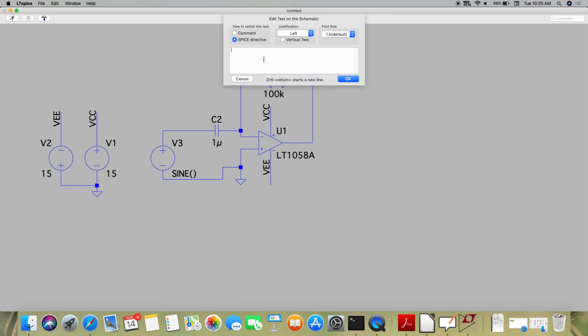I'm going to tell you how to write the netlist, or we will generate it automatically first and then I'll teach you. But if you don't know how to write the netlist for giving the analysis type, you need to go to edit and then to analysis command.